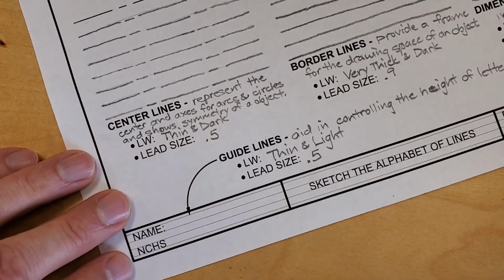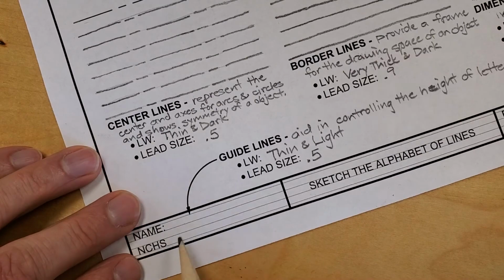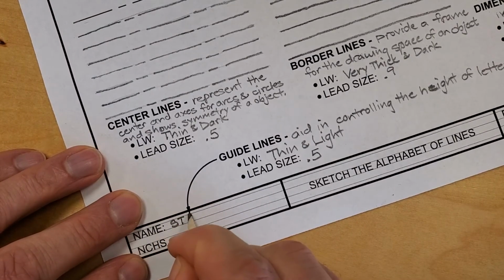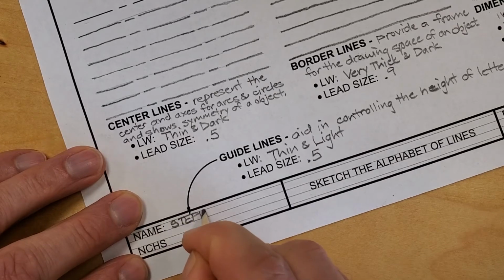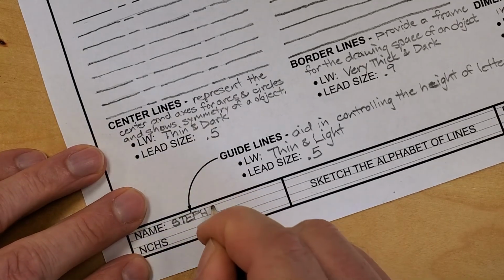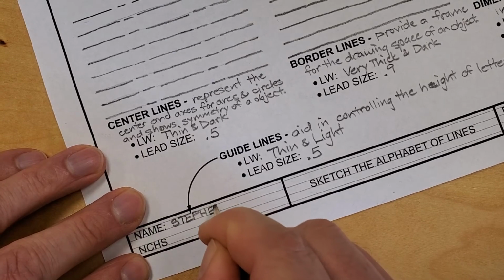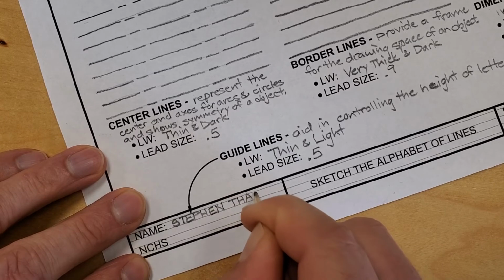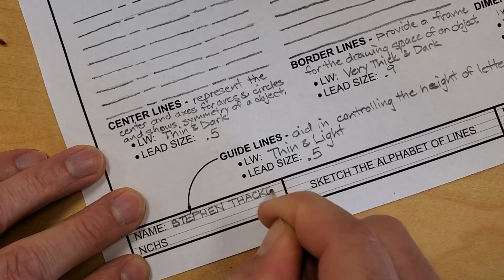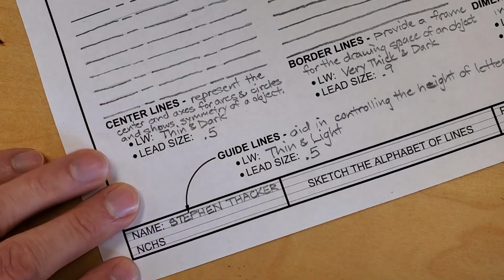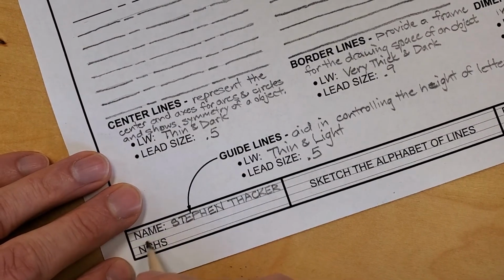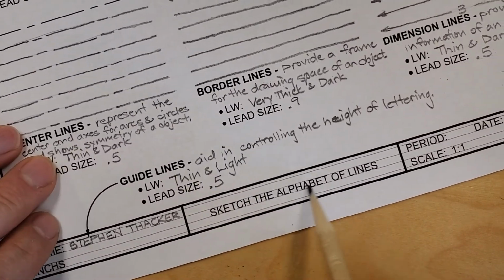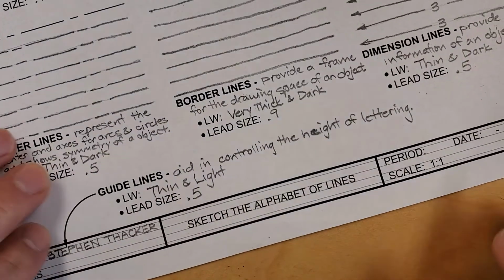What we want to do is apply our lettering. So remember that lettering is vertical uppercase Gothic lettering. So what we want to do is put our name in here. And my pencil's a bit dull, so it may seem like that information is kind of running together a little bit. But just watch your space and be sure that your lettering is uniform. Okay, you want your first and last name. The school is already in there, CHS. Your title, hence why it's called a title block, is already located in there as well.